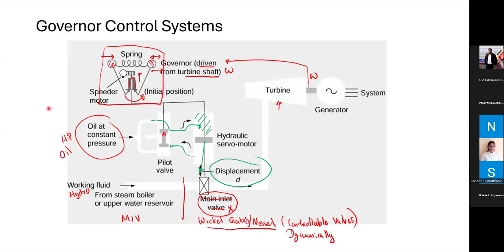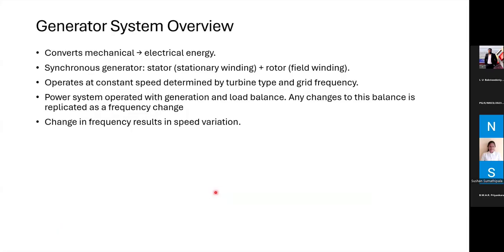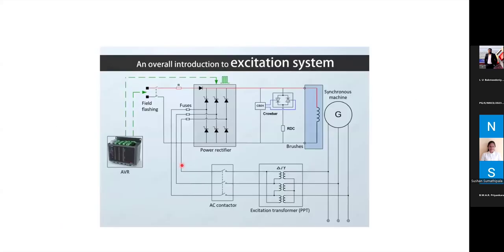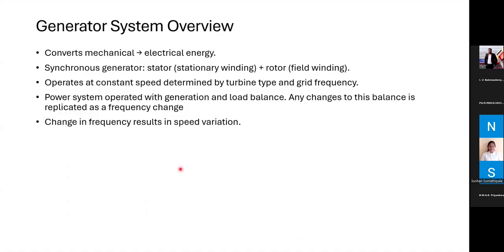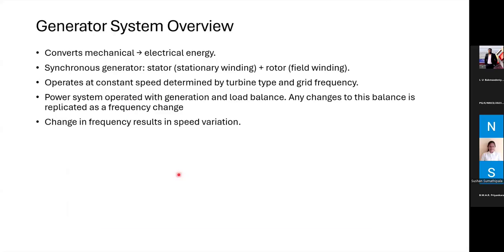So this action is typically with regards to the electrical dynamics on the power system operation. The governor is relatively slower compared to the electrical dynamics, like the faults or load changes that happen. So there are different dynamic time frames or time constants associated with the electrical power generation in hydraulic generation schemes. So it is necessary to properly identify them.